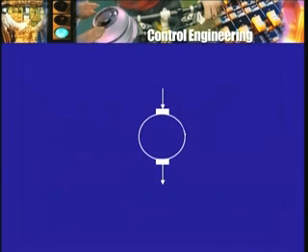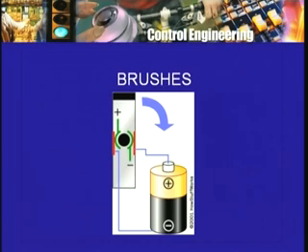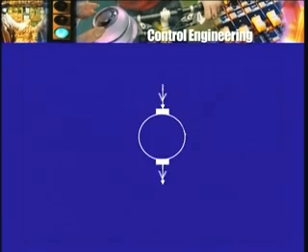So here is the symbol for the motor armature, and two little things are placed at two ends of a diameter, and these are supposed to represent the brushes that press upon the commutator. So here are the two wires that are connected to the brushes so that armature current can be made to flow. Remember this symbol of a motor armature with a pair of brushes.